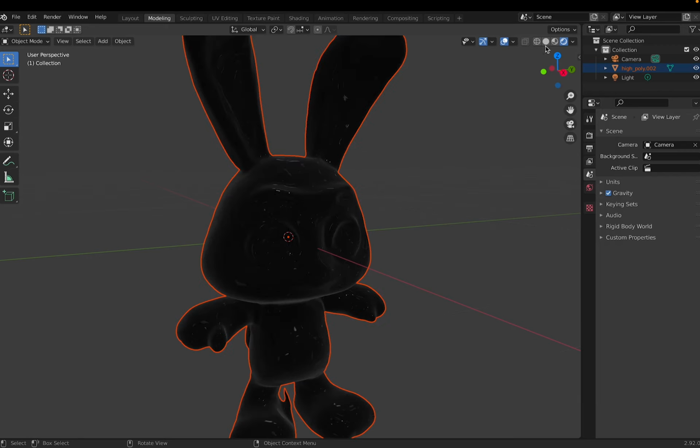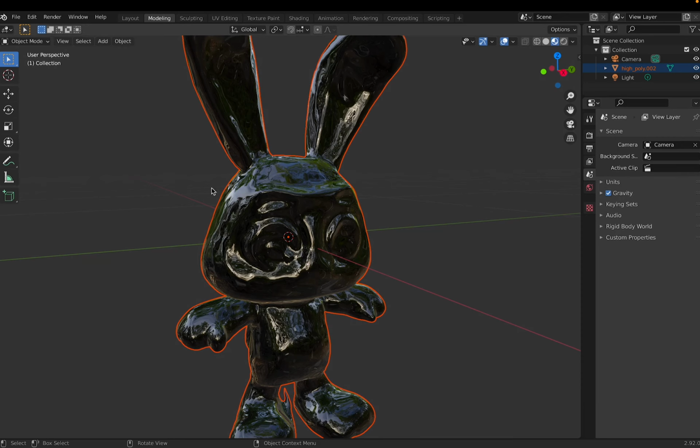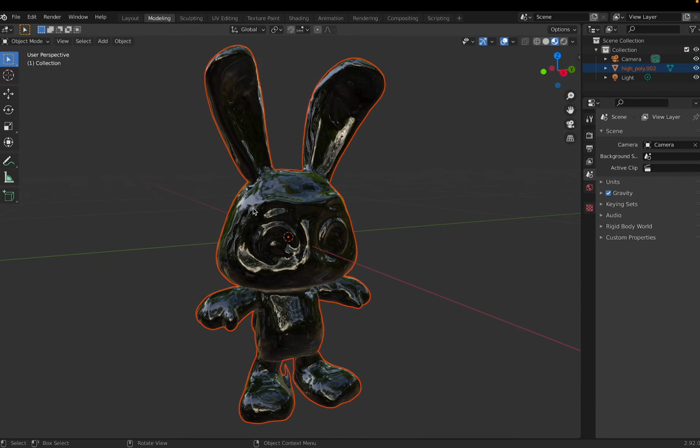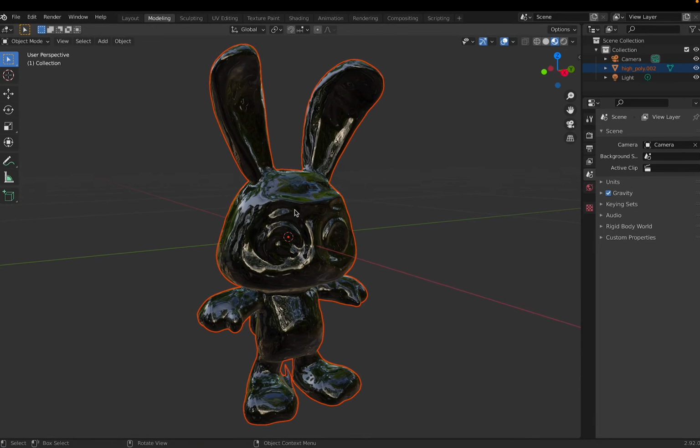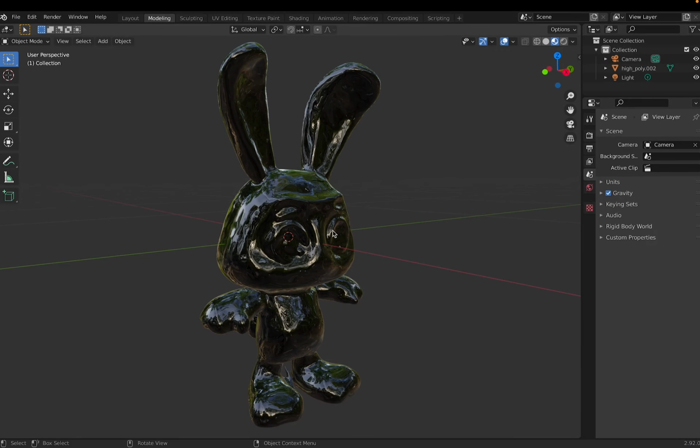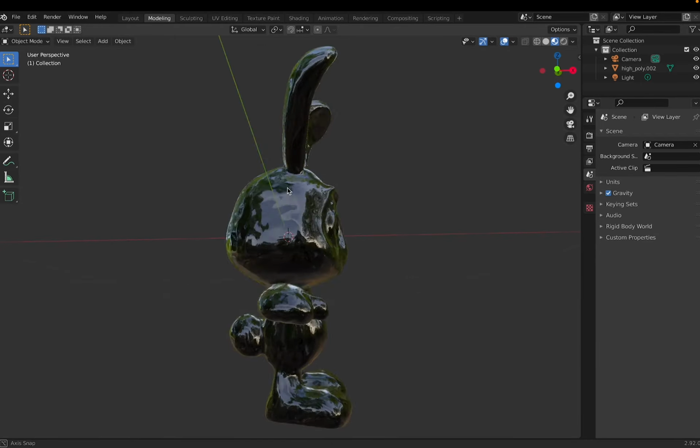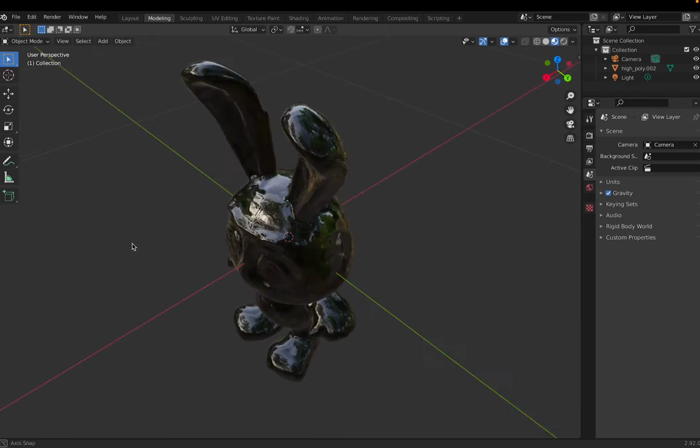So this is with the shading and the materials, but I think it puts the roughness or the metallic texture on there, but I don't get the same detail that I had in an FBX. So I'd probably recommend exporting FBX if you wanted to use the shading from the Genie. If not, if you just wanted to redo the materials, I think this would be okay.